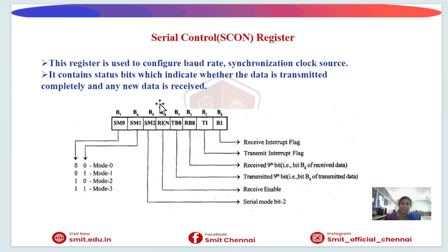Next one is the serial control. The SCON register controls the serial communication in the 8051. The function of the SCON register is to configure the baud rate and the communication mode. It indicates transmission and reception. SCON is an 8-bit register. It controls UART operation in the 8051.